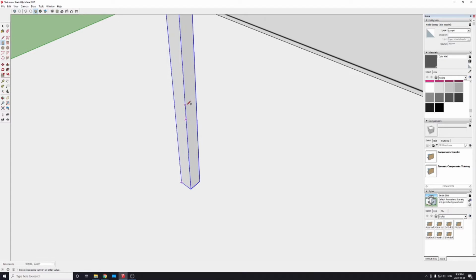and left click on this edge, and just randomly, I can do this at 2 inches, comma 2 inches. That'll give me a nice rectangle on this edge. Now I can go L for line, and I'm going to left click this bottom corner, and move up this wall here, and go 8 inches, enter.